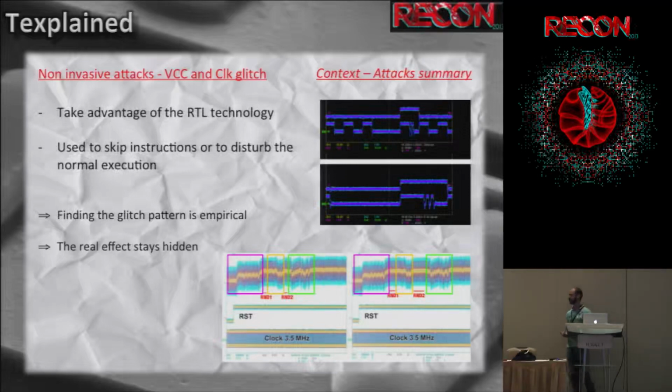But with these techniques, it's a lot of trial and error, and I don't like it so much because of that. You spend so much time trying to find the good shape, the good timing, and everything to extract the code that it's just losing time, you know. And on the latest chips, you can try this kind of method, playing with the clock or the VCC, and it will not work anymore.